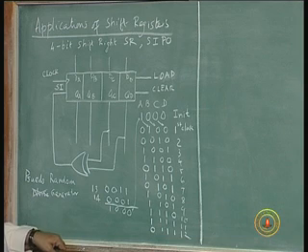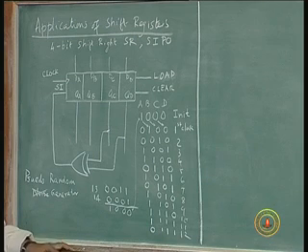What I mean is, suppose you want to have a pattern verification pattern, you put a bit pattern which is accepted, and for that bit pattern you know the sequence it has to come. So, you can know whether there is any error in the transmission, if you agree on the initial pattern, both the sending and the receiving end.